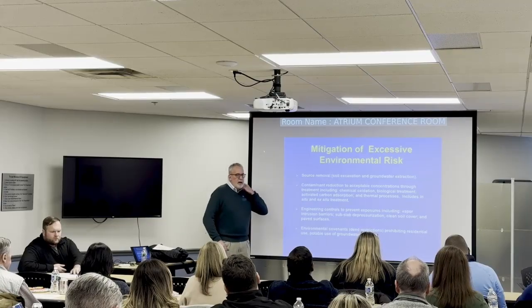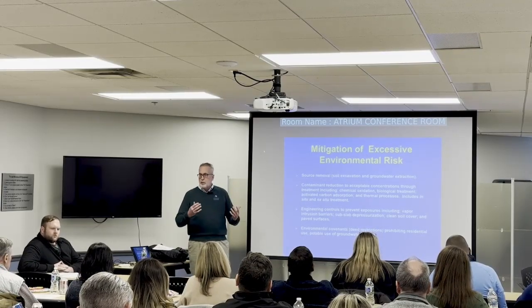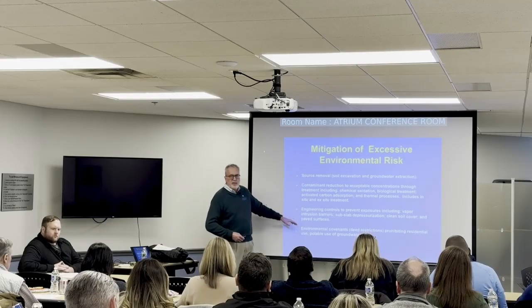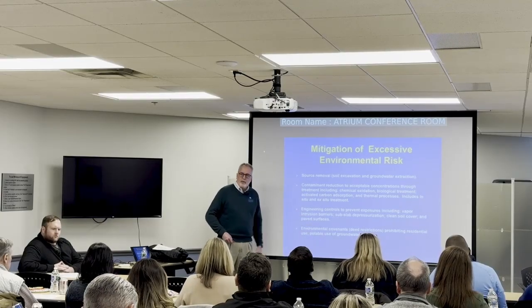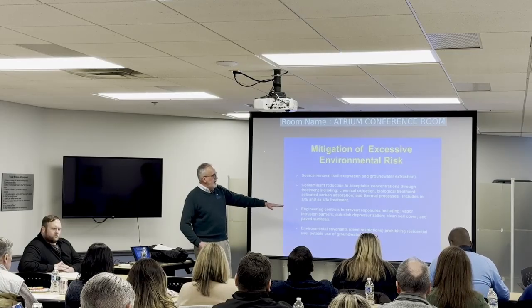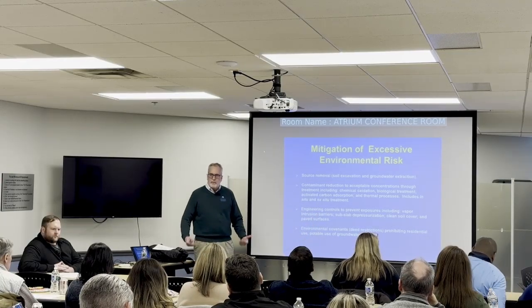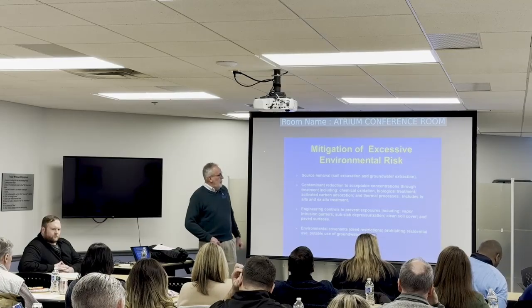You can't use a property for residential purposes, so that you have commercial exposure scenarios. Engineering controls: vapor intrusion barriers underneath the floor slab of the building, or a subslab depressurization system, like a radon type system, to minimize potential for migration.